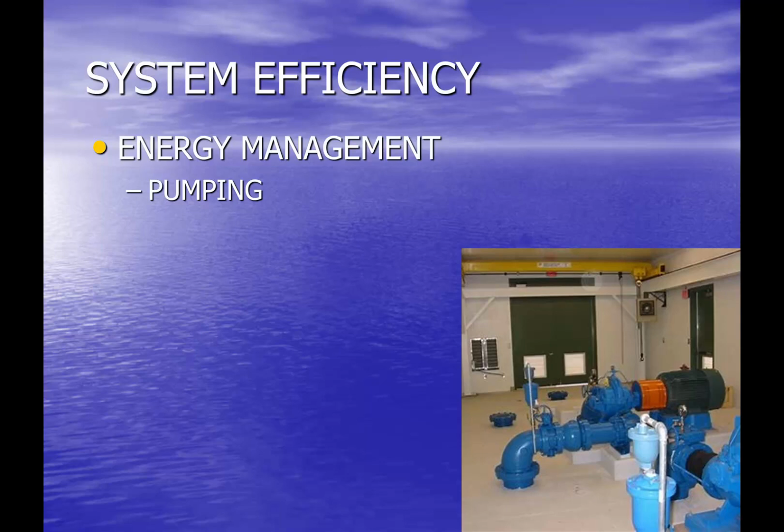So it's looking at reducing pumping where necessary. It's maximizing the efficiency of the pumps. It's doing proper maintenance on the pumps so they remain as efficient as they can be. It's looking at what the valving is on the pumps so you're not overly eating up pressure that the pumps have to provide. So looking at being as efficient as possible with our pump stations is part of the overall efficiency management for a water distribution system.